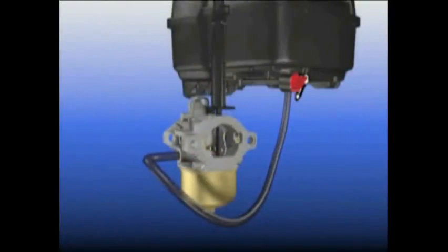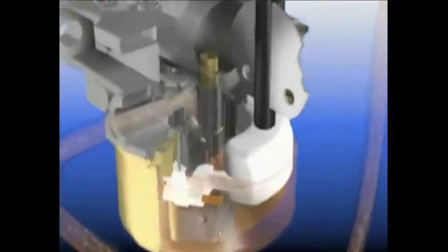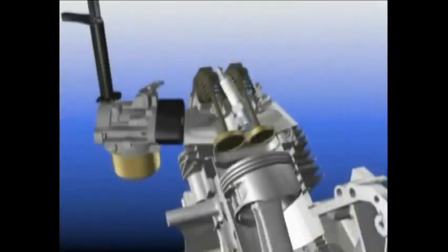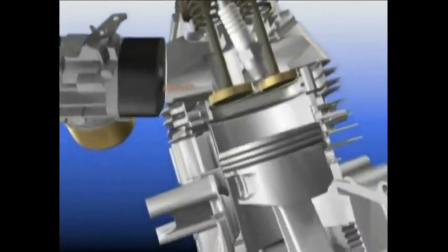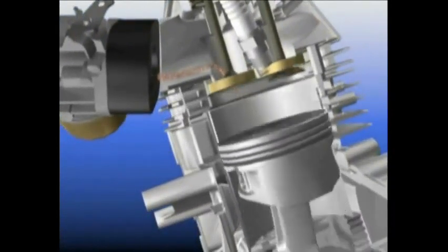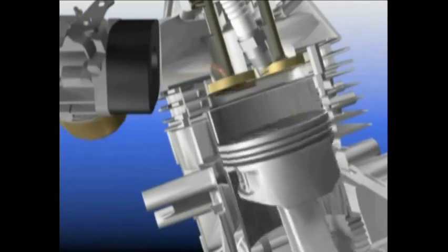The symptom of oil dilution when the engine is not running is typically caused by dirt or debris becoming wedged between the carburetor's needle and seat. It can also be caused by the float hinge pin sticking, or a defective or misadjusted float. When this occurs, it allows the fuel to continually flow through the carburetor intake manifold, through the intake valve, down the cylinder wall, and into the crankcase. This condition is called cylinder wall wash and will eventually cause a failure of the piston rings and cylinder wall.